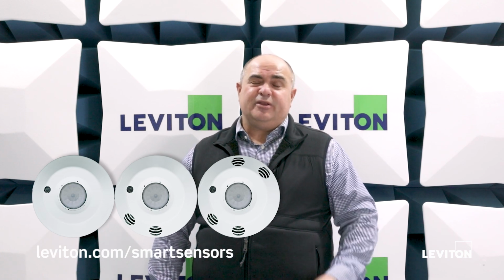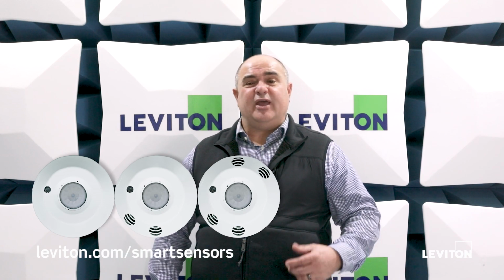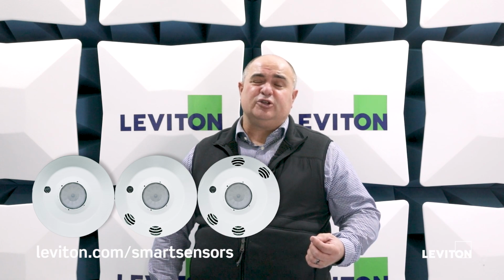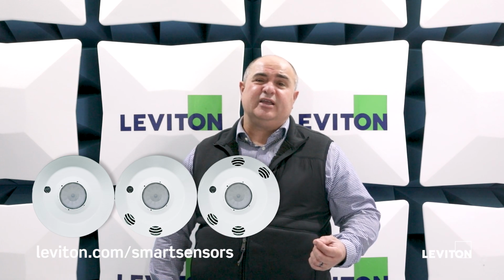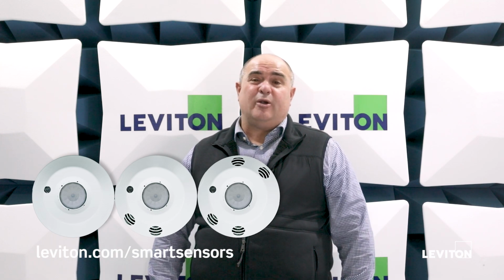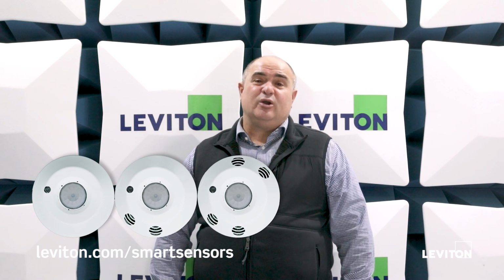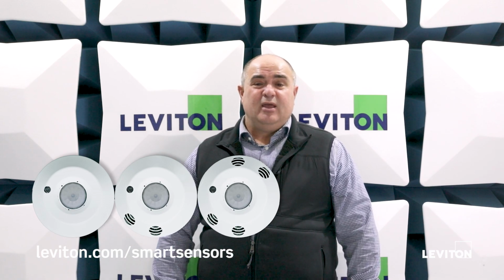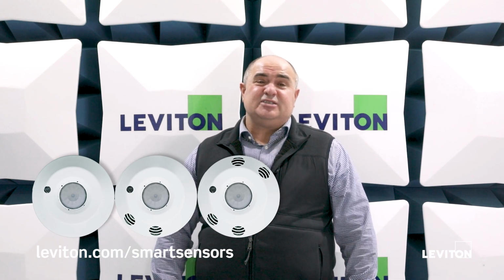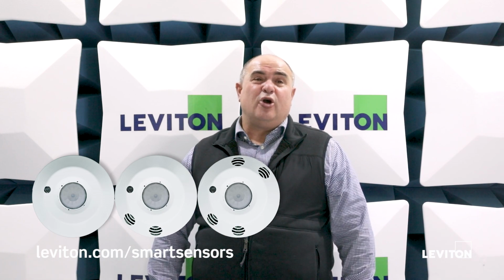So as we developed the Smart Sensor ceiling mounted technology, we came up with a room controller that actually will do the 0 to 10 volt control as well as the true daylight harvesting. But then we also realized that there were certain code requirements that limited the control requirements to simple switching within a given space. And if we look at this, we're really looking at just 2 devices to meet all of the code compliance requirements in a larger area.